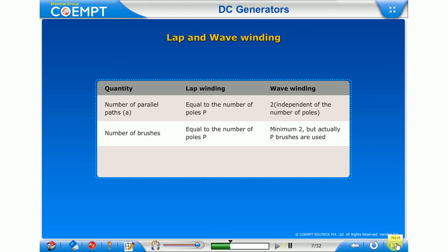As the coil continues to rotate further, the rate of change of the flux linkages and hence induced EMF in it increases till position 3 is reached, where theta is equal to 90 degrees. The coil plane is horizontal, that is parallel to the lines of the flux. The flux linked with the coil is minimum, but the rate of change of flux linkages is maximum. Hence, maximum EMF is induced in that position.